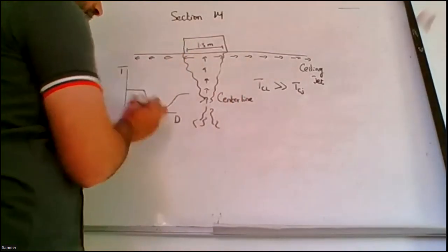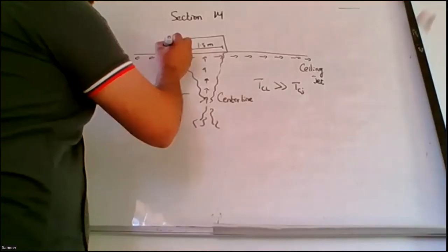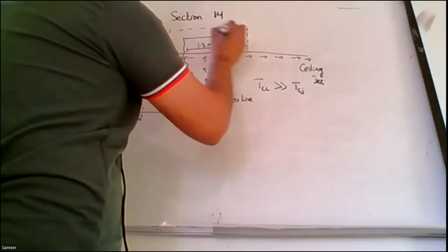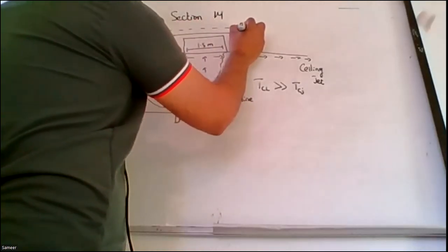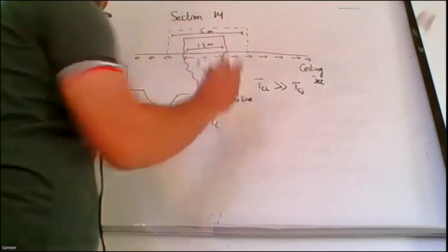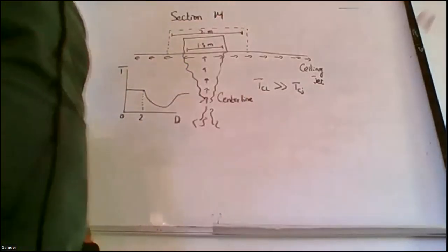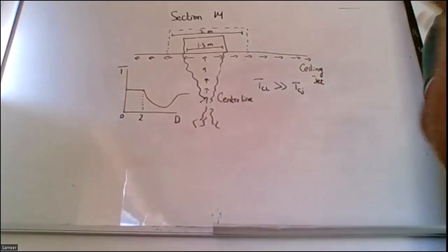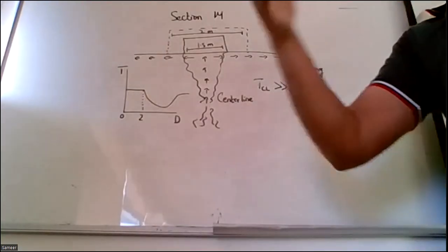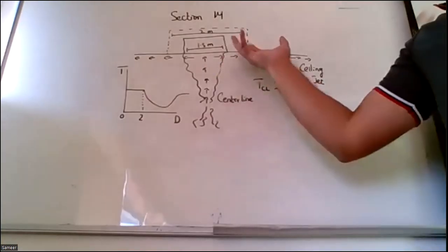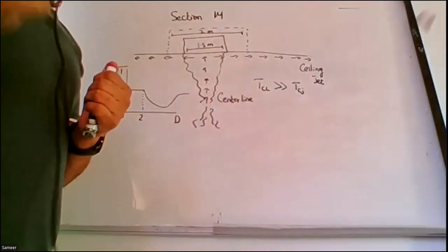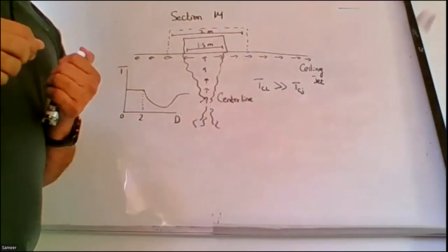And then the area of effectiveness is up to 2 meters. So all in all, 3.5 meters is the area up to which the heat can be distributed, approximately, up to a point where the difference will not be that much. NFPA 72 says, how much should be the distance between heat detectors?